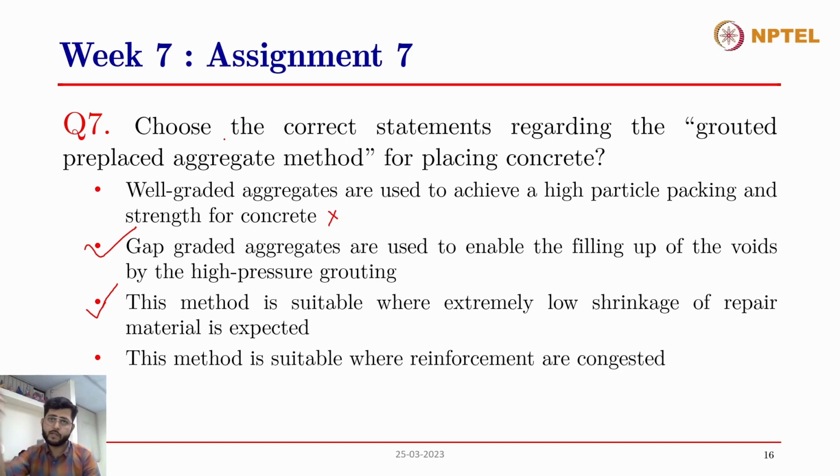But what we are doing is we are only pumping the grout, and we're expecting the concrete to be formed within the formwork inside the structural element. So what we need to do is place gap graded aggregates inside the formwork at the structural element location. And now we are pumping the grout.